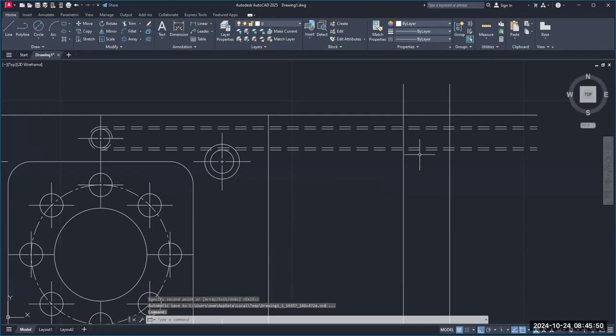Now, Mr. Morris, what do those dashed lines mean? They represent this tapped hole, this threaded hole, and these are the lines. Now, if we want to clean up, if it's starting to get kind of confusing, which it is, we can go ahead and use our trim. A little pair of scissors here, and just trim these lines out.